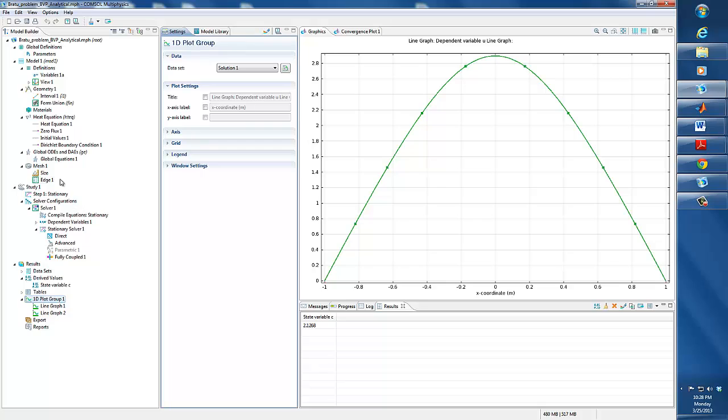Some of you have asked why you see a difference between the analytical and numerical solutions calculated from COMSOL. Most likely you are plotting two different solutions for a given epsilon value. By changing the initial guess, you can change the solution.